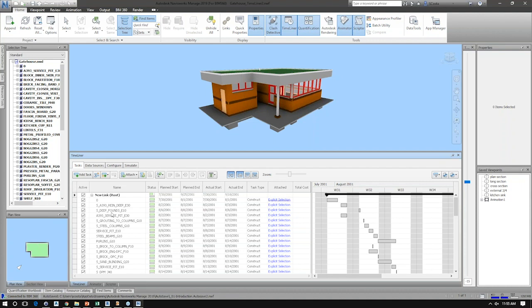Why is this an issue? Well, certainly when you receive information from a consultant or you're running the Timeliner yourself on a project that you developed, you're not building a Revit project file in the way that a real world project is constructed. What's the simplest example of that? Well, floor slabs. So suppose for a large project, you're pouring an enormous floor slab, and that's going to be broken down into several tasks as the pours happen on various days. Well, a Revit slab isn't modeled like that.